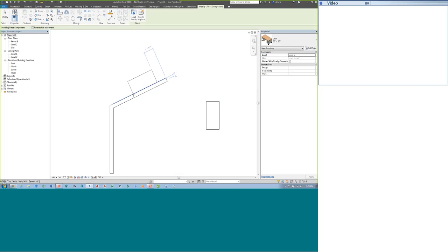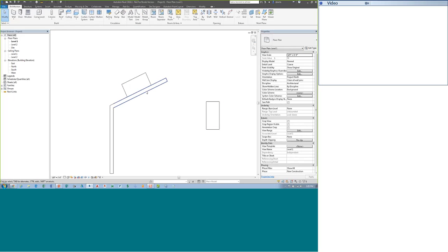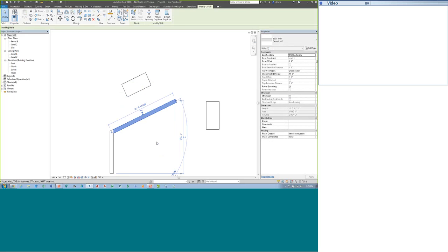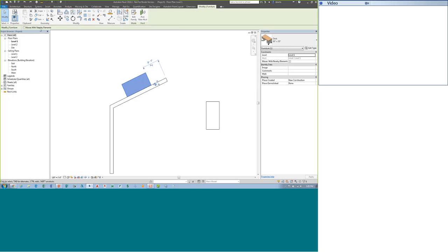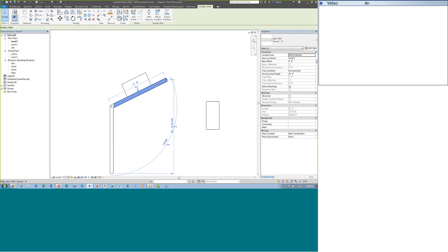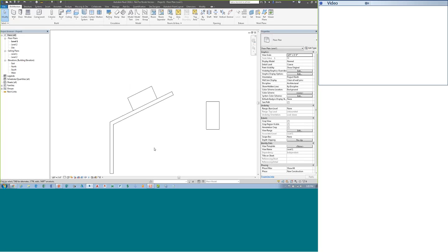Create similar, and I'll hit the space bar to align it. Okay. So now that it's aligned to that entity, if I select it, that is not checked. So it should not affect, see? Whereas if I undo that, select the desk, and hit moves with nearby elements, it should be affected now. So I probably would have to say look at the Revit file to see what's causing that hiccup. But by default, the move with nearby elements should not be checked.